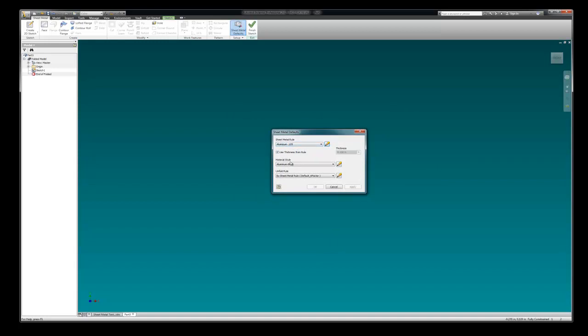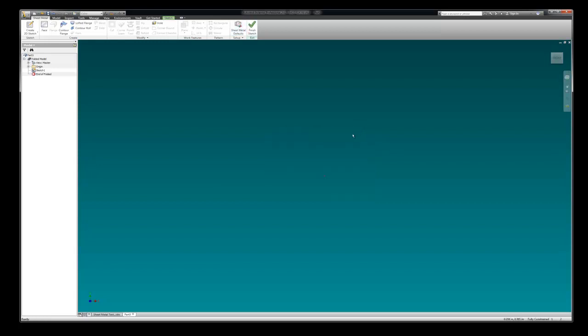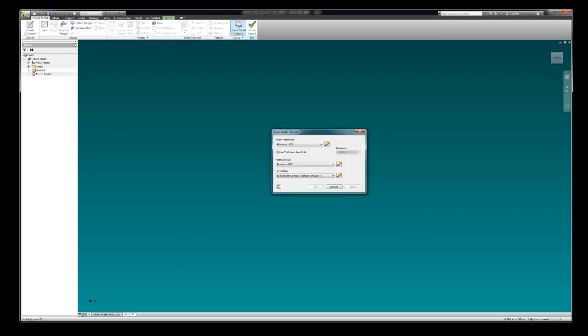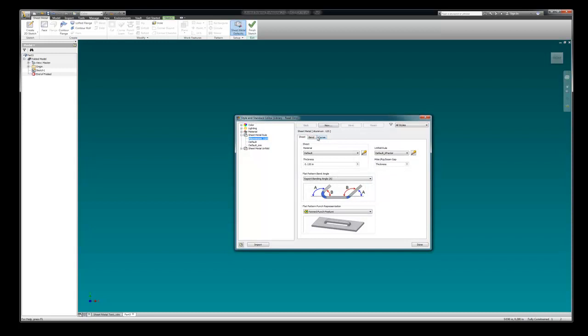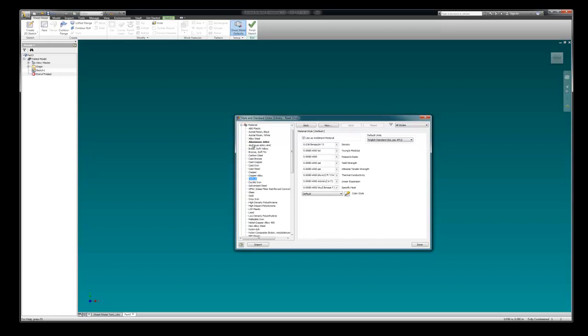That was the name that we called it. We've picked our material right here, and we're going to do our sheet metal rule using the K factor, and that's a standard bending algorithm that they use. Okay, so it's the default. And use the thickness rule, and so that means it's going to be the 0.125. Okay, so we're going to go OK. Now there's some other stuff we want to do there too, which I didn't pull up, and that's when we get to here. Okay, so we're at aluminum 125. The material is our default 6061. You can see that's already picked. Okay.